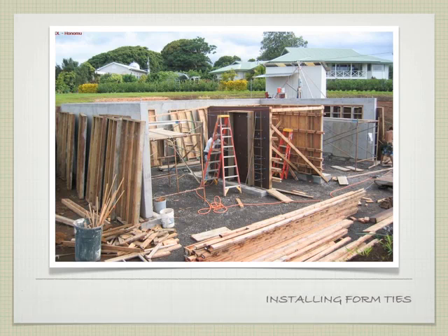There it is from the outside. So we see the surface of the plywood, and the form ties are sticking out. This is all braced on that side. There's the keyway. You can see that little piece there. Each one of these is a form tie. You can see the rebar starting to be put in. It's not finished yet. Anybody recognize what that would be? Ultimately, it's a doorway, so we need access to this piece.